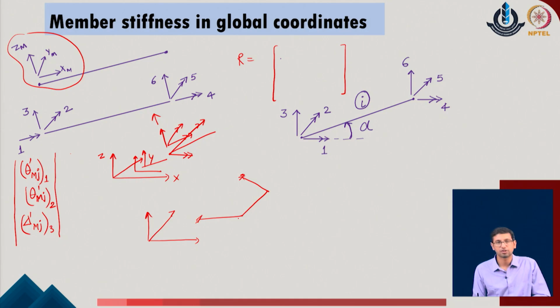Say one of the members is in the same direction as the x coordinate. So for this, the x direction will come out as the global direction of the given system. The second member, which is this one, will have local directions, or member directions, appearing like this. So the moment which we will define at any point in this given member will appear along the same two directions of the given system.